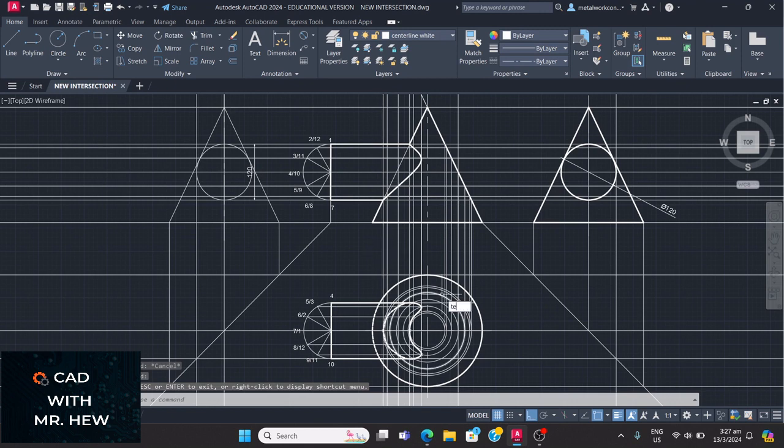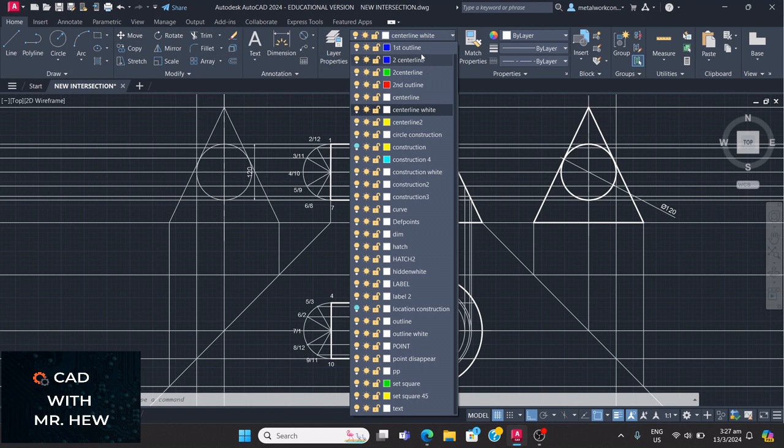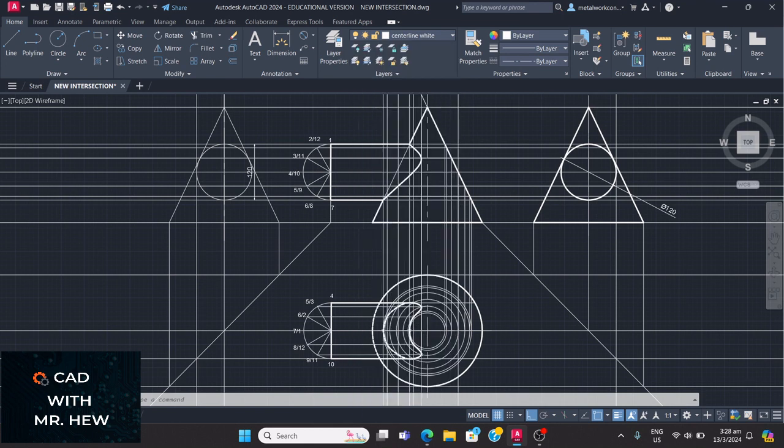So we're gonna label the front elevation. If you draw the projection symbol, I need to put this on the layer. So watch now. We're just gonna click this, click this, click this, click this. Oh, we need to draw the base. It's going to highlight the entire construction line running horizontal, like the X line. So since we have to draw it, we just put it there, all right?